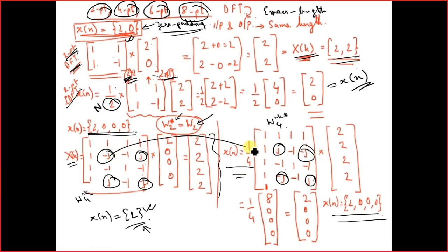So see, all of them are having opposite signs. So if you calculate the normal Twiddle factor matrix, you can easily calculate the conjugate one, and you can use it easily for the IDFT purpose.